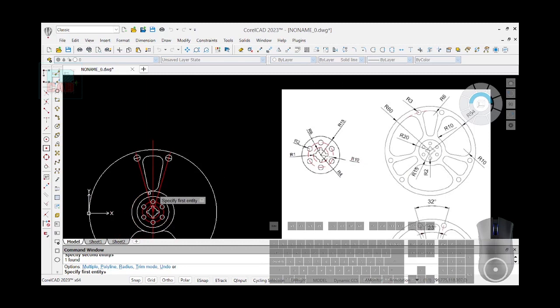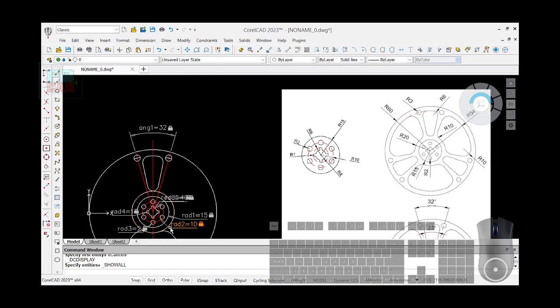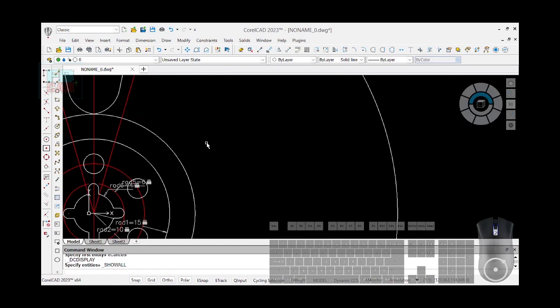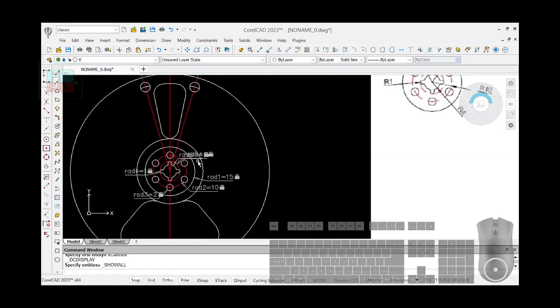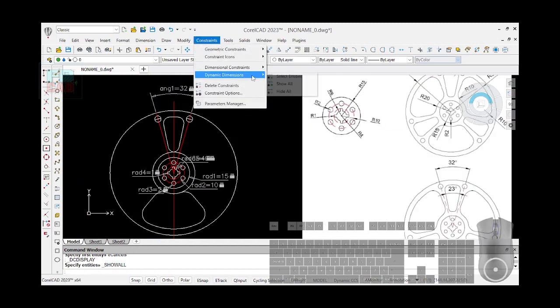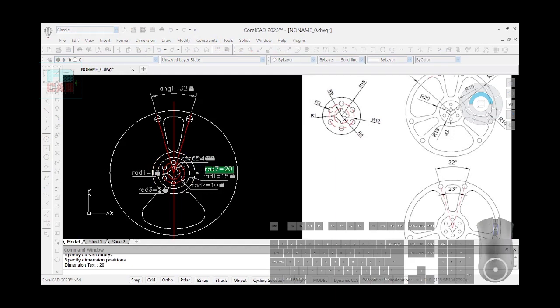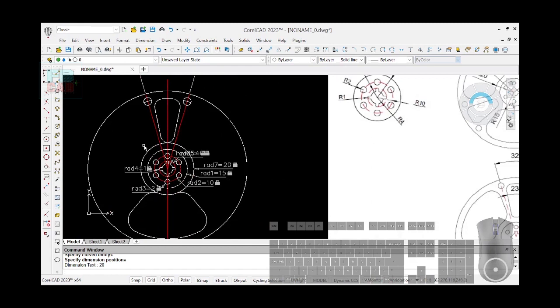Yeah, this is one of those challenges you face when you are working. All right, let me see. Show dimensional constraint. What's the radius for this particular circle here? This particular circle is not stated. So let me use my dimensional constraint and make sure I'm correct. So I want this to be 20. Okay, 20. So being 20, we are good to go.